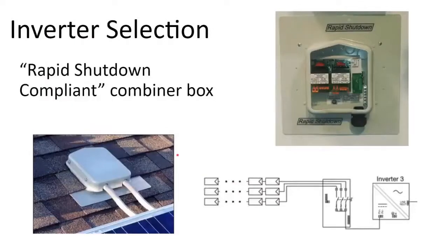Where some of these line diagram creation tools fall short is the balance of system material, wanting you to detail exactly what it's going to be out in the field in construction. So for instance, here's a popular rooftop transition box for transitioning the cable to go down into the attic, and being able to interrupt these home runs and say, no, no, no, right here, I want a junction box to transition into the interior of the attic. Sometimes that level of detail needs to be kind of re-highlighted in CAD.